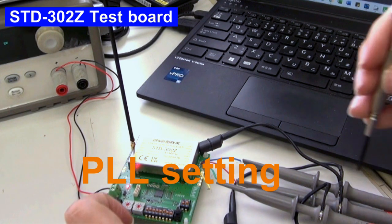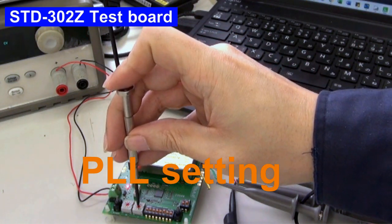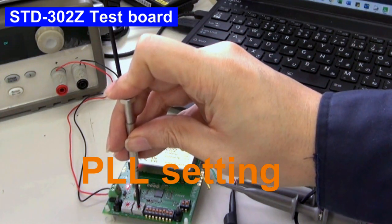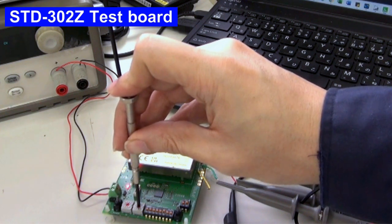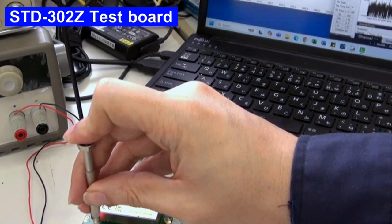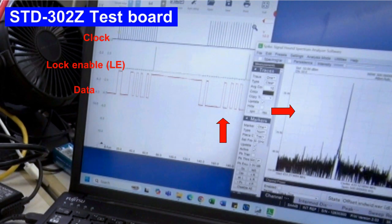The board's CPU sends the PLL setting to the module every time I change channel. Even with no data, we can still view the carrier. When I change the channel, we can see the values being input serially using a clock signal.